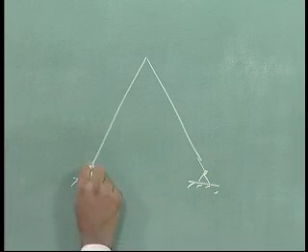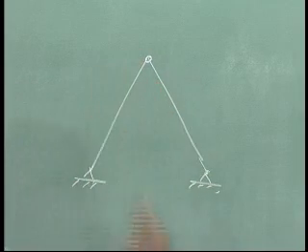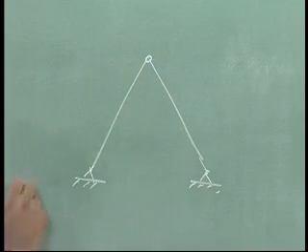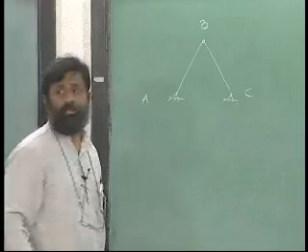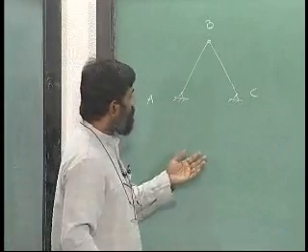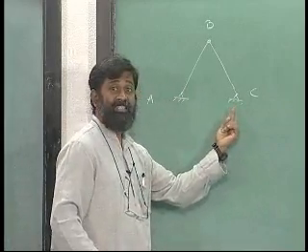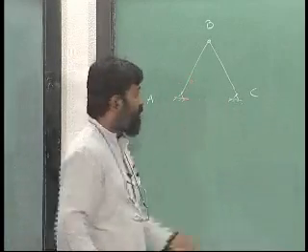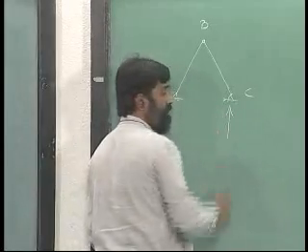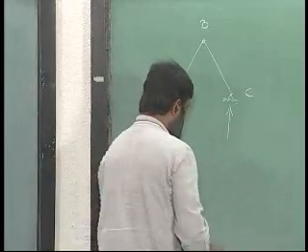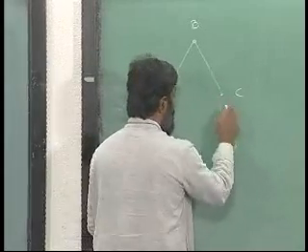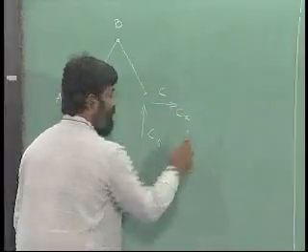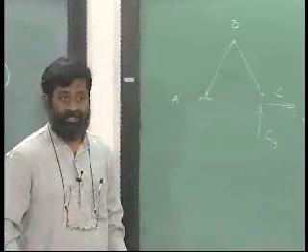We have two pinned supports here, and a pinned joint over here, ABC, as we know already. I am not denoting the external forces here. If I have to find out the reactions here, there are two reactions. One is vertical, so if I remove this pin joint, I have Cy and Cx. I need to find out both these reactions.